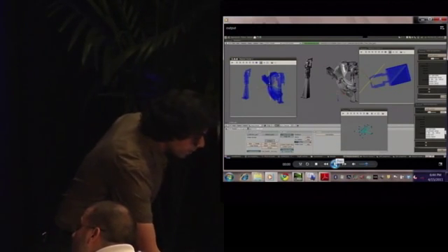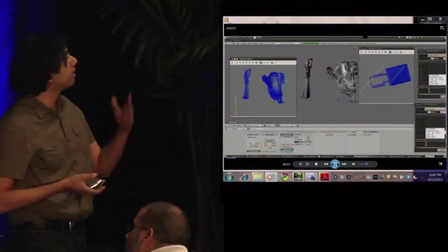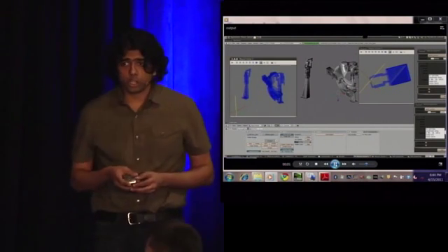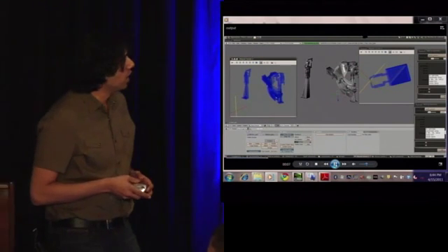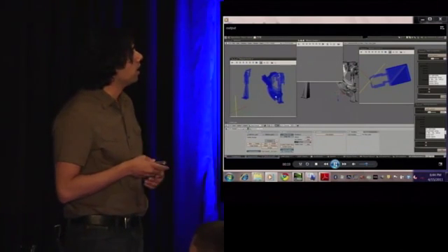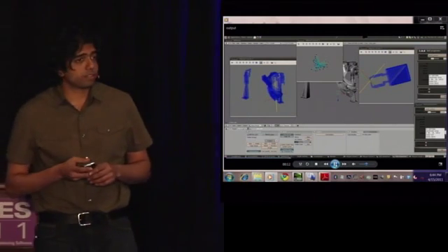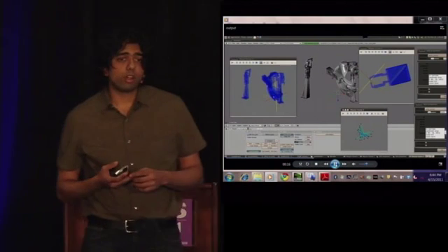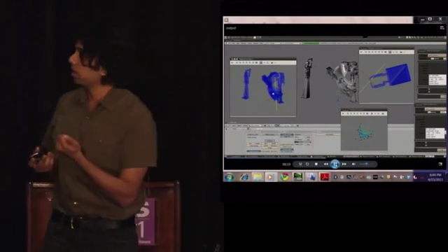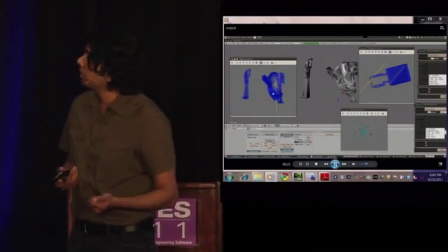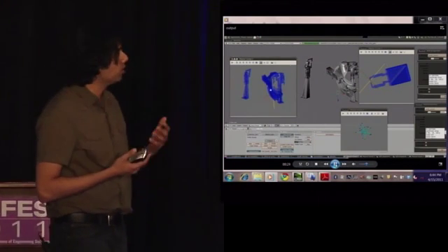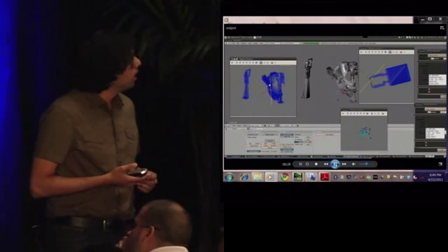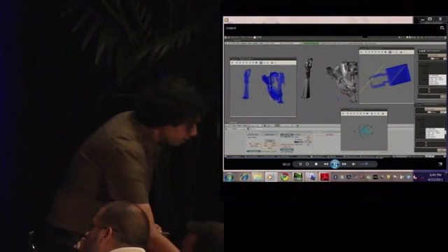So in the center, you have a CAD model of the tooling layout, and on either side, we have voxelized models of the geometries interacting. And what I'm doing now is clicking on different points on the work part surface from the voxelized model, and you can see interactively, I have a map of all the colliding orientations of the robot that are generated at each point. You can see that it's generated on the fly right away as I go through different points on the work part.